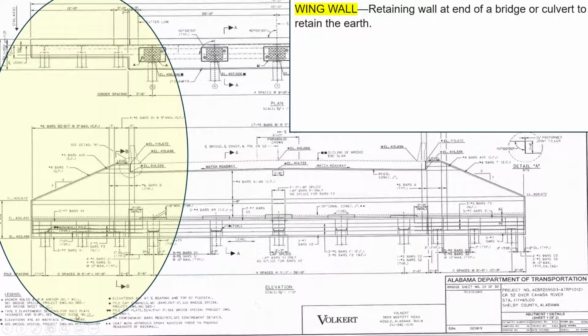And as we discussed in our past videos with the cross-sectional cuts, you've got your cross-sectional cut A and B. A represents your abutment where your actual roadway is going to sit, and the B sectional cut represents your wing wall. And if you look up here at your plan view, you'll notice there's a big difference between how your wing wall is built and your abutment seat.